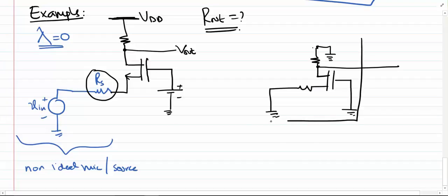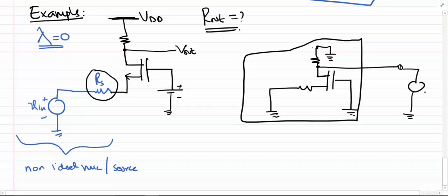And then we have to apply a voltage source externally of Vx, due to which a current Ix flows, and the ratio of Vx and Ix will give us the output impedance. So here we have Rs and here we have Rd.